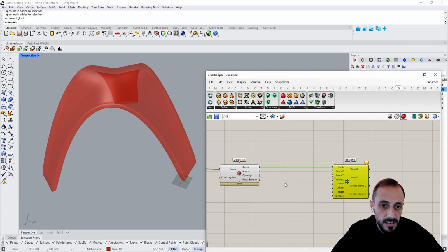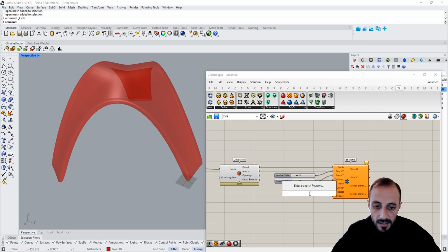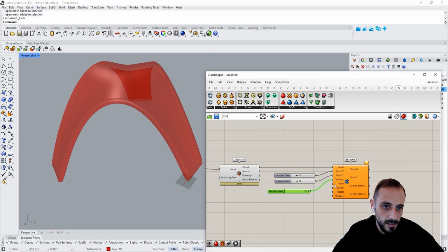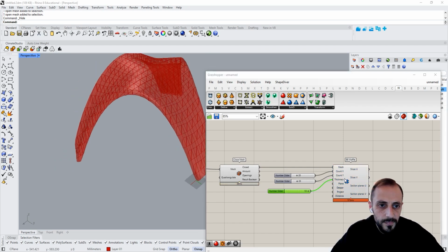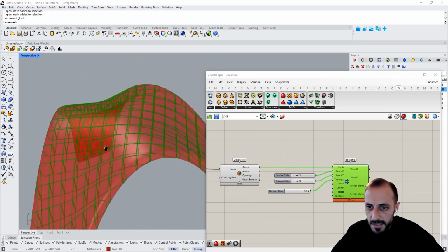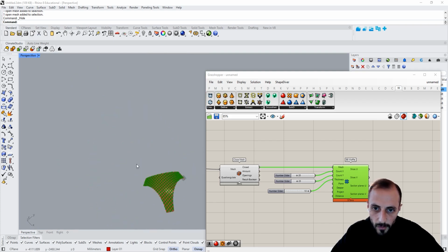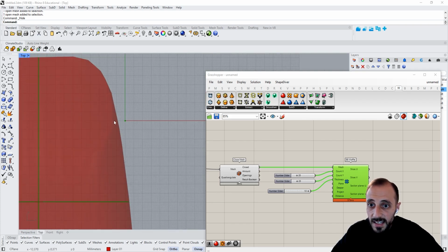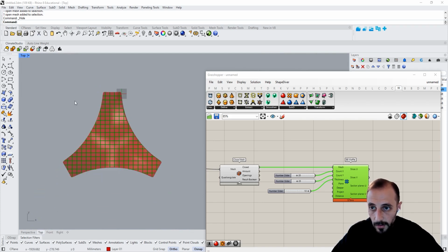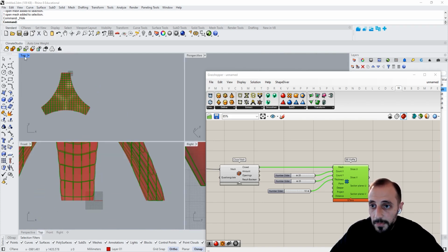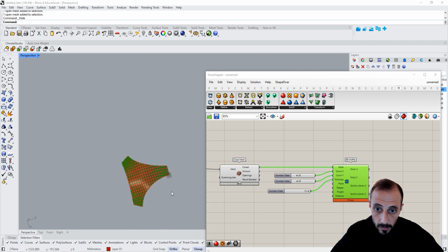We can count this, right? We can say 20 by 20, okay? And we can put a thickness of 10. This is the material thickness, so 1 centimeter of the material thickness. And you see, now we grab these pieces here. And if you look at it from top view, what we are seeing, the plane is XY plane, right? And which is something as a default value here.